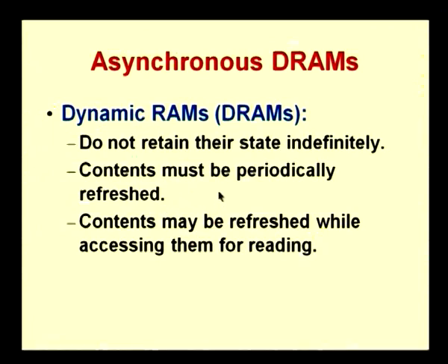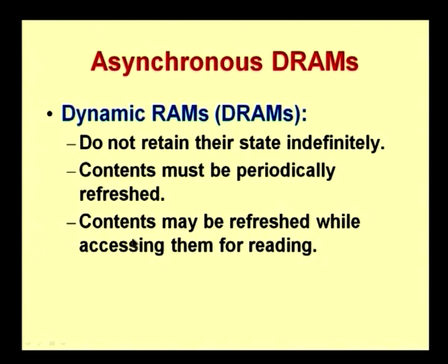What we are saying here is that after some time the data is likely to be lost. Because it is likely to be lost, I will have to store that value back again. I will have to write it back and make sure that the data is maintained at the same value. How do I do this refreshing? Normally the contents may be refreshed in dynamic RAMs by accessing them for reading. If you just access it once, you will find that it is again refreshed.